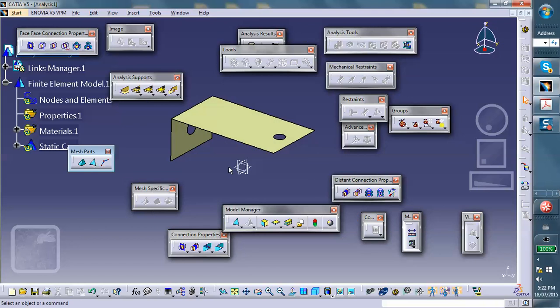Also notice that if I'm asked to use full symmetry, I need to cut this thing. I don't think symmetry was actually used in the book, so I'm not going to cut it here, but when I do it the second way, using the direct approach in the wireframe and surface design, then I'm going to cut it, okay? So I am not using plane of symmetry on this one. On the test, you will be asked to use all planes of symmetry if applicable.